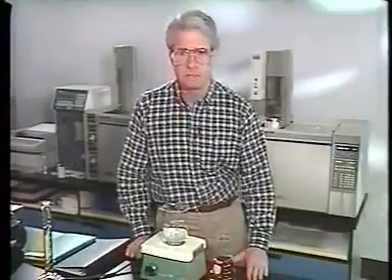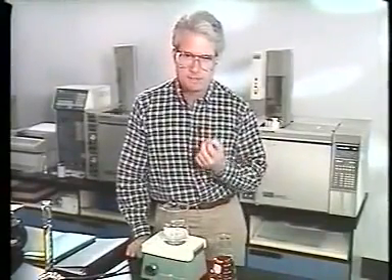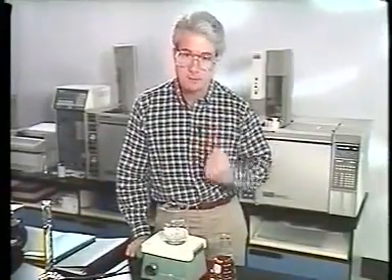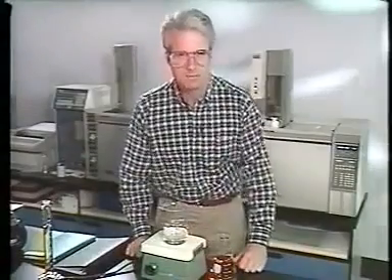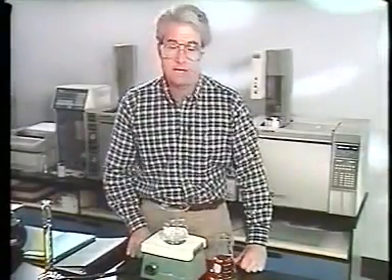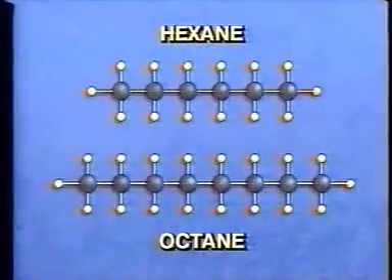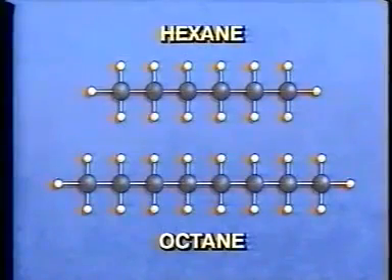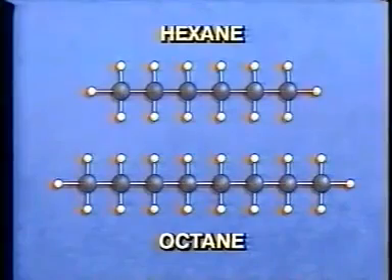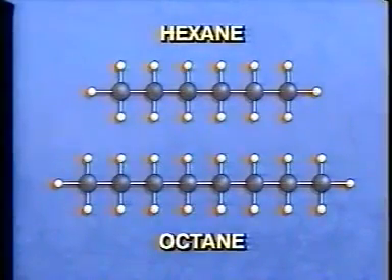Hydrocarbons vary in molecular weight. As the number of carbons and hydrogens changes, one of the physical properties that's affected is its vapor pressure. Let's examine vapor pressures for different hydrocarbons at a specific temperature. Hexane is lighter than octane because it has fewer atoms in its molecule. If both gases are at the same temperature, the molecules of hexane move faster because they're lighter. Since this is the case, hexane needs less heat to go into the vapor state.